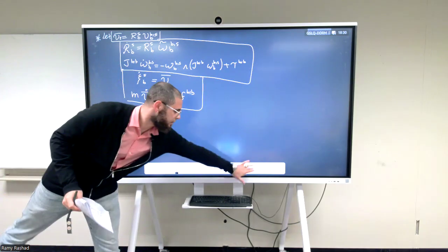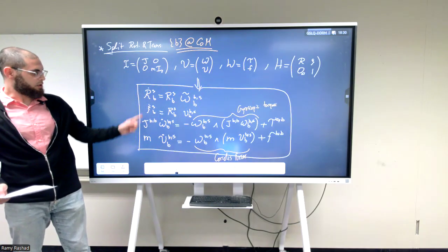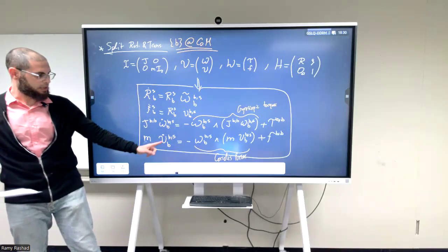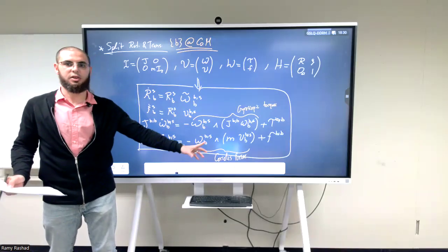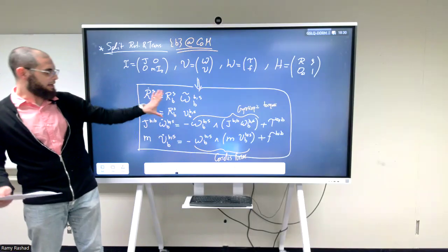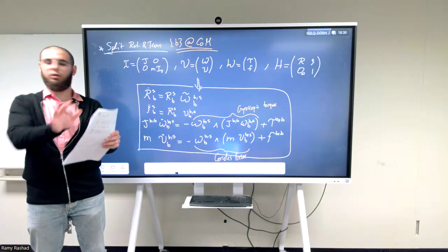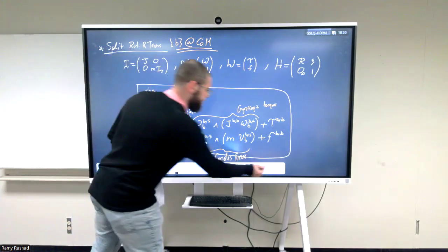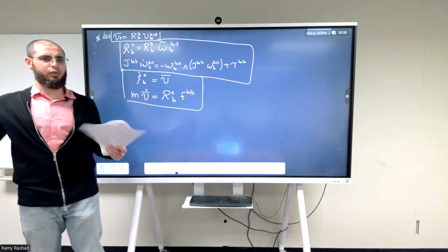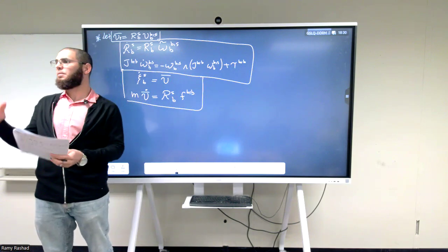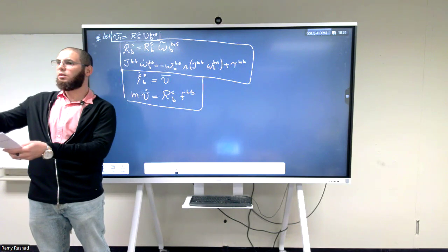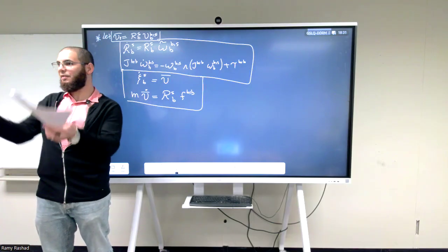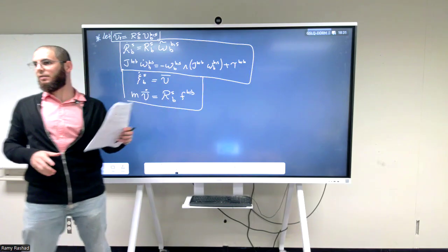You see it in this form of the equation. You also see it in that form of the equation. You see here when I had psi dot equal to R multiplied by V, and the V dot takes the angular velocity into account. There's a cross product there. So the rotational dynamics live on their own. The translational dynamics depend on the rotational dynamics. That's why in control, as a strategy, they sometimes design a controller for the attitude, and then design another controller for the position separately. And they have it in a cascaded form, just because of this fact.